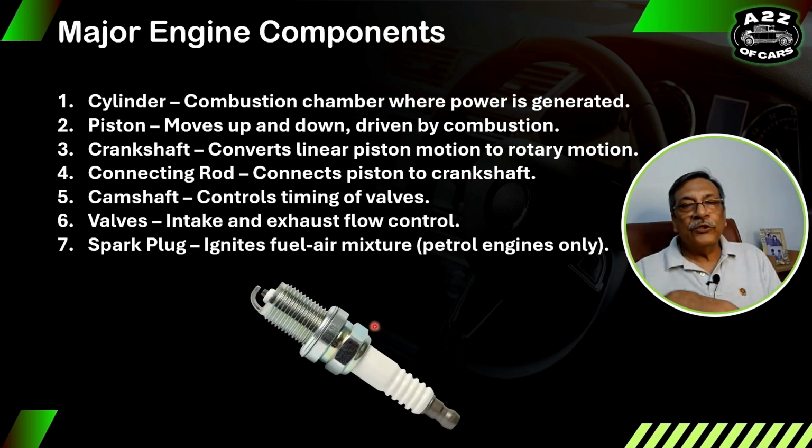Spark plug. Like I said, in the petrol engine this actually gives the spark. Here there's a high voltage wire that is connected to this from a coil. And now we have SDLI, the smart distributor-less ignition system. So every plug has a coil.